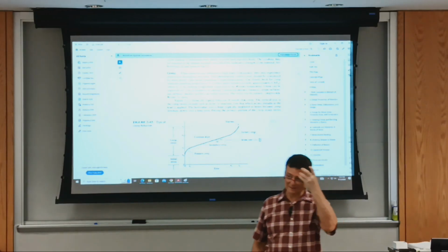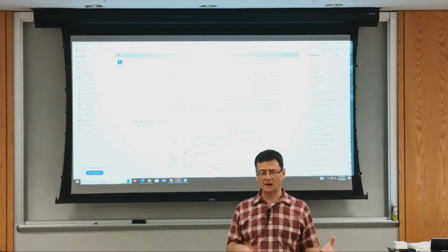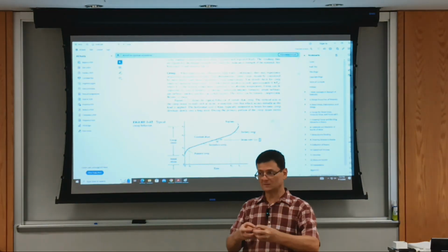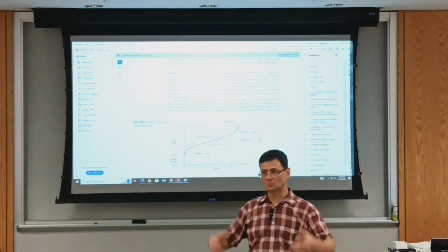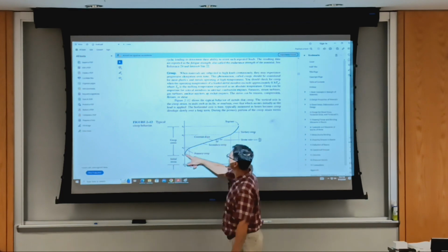It's also called stress relaxation for other applications. So you tune a guitar and you put a guitar under your bed, and in 6 months it won't be tuned. You need to retune it. It's both the string and the guitar itself that gives way. But creep is considered primarily for elevated temperature.